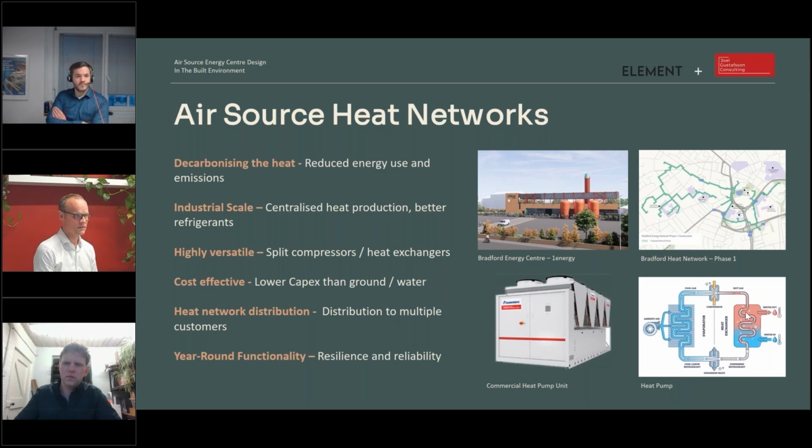There are water source networks as well, of course. And the heat network distribution pipe takes heat from these central locations and puts it into a network of pipes at whatever temperature suits the needs, to distribute to multiple customers, residential, commercial. So you're taking all of that challenge of generating heat and putting it in one location to give year-round functionality for resilience, reliability. There are interfaces with cooling, the use of waste heat and diverse heat sources as well. So that's really a rundown.